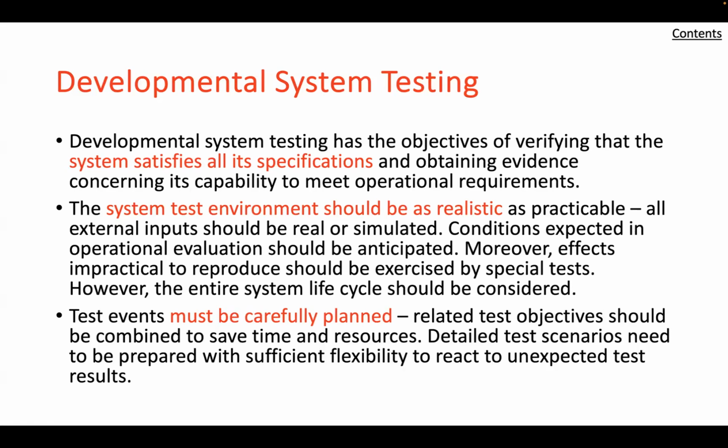So for system input and environment: one, the test configuration must represent all conditions that affect the system's operation, including not only the primary system input, but also the interaction of the system with its environment. Two, as many of the above conditions as practical should be exact replicas of those that the system will encounter in its intended use.